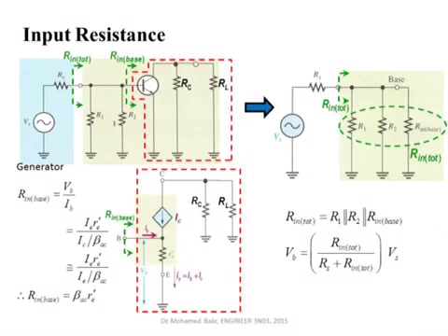Okay, so now we are ready to start analyzing this one. When I say calculate the input resistance seen by the source, then I would like you to find the ratio between Vs to Is. There will be a current drawn from this source. This is the meaning of the input resistance. Calculate the ratio between Vs and Is when all other sources in the circuit are removed. This is an AC analysis, so we don't really have any other sources other than this Vs.